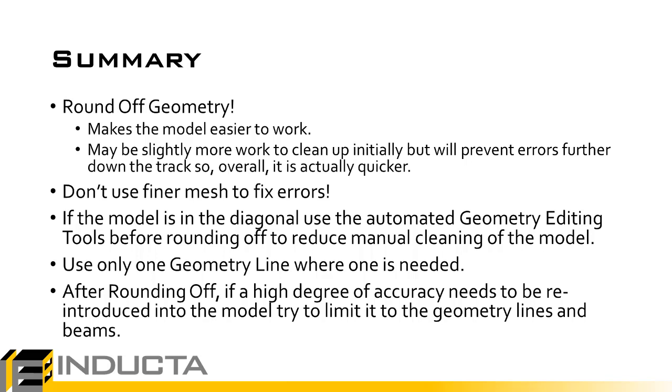But it's also important to understand what the geometry editing tools do, so that if we have to perform those operations manually, we can do so. Another key point is only use one geometry line where one is needed. So this makes the model lighter, simpler to work with, and there are less locations to fix errors in.